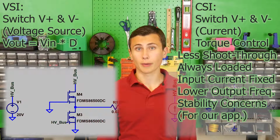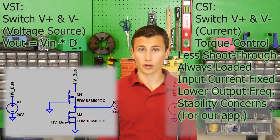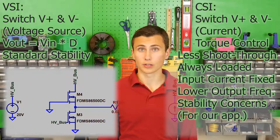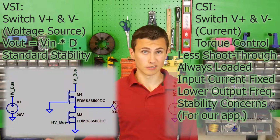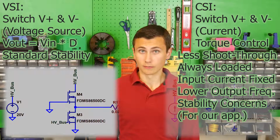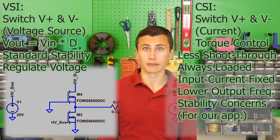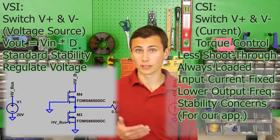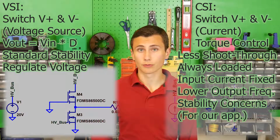The stability of this topology is not dependent on the load, and really has less stability criterion than the current source inverter, just the typical gain and phase margin required for any control loop. These are typically what are used in voltage regulators, like an inverter output, since they regulate voltage. It seems obvious when I say it like that, but I'm just saying something obvious in hopes that it makes the point easier to remember. So voltage source inverters then.